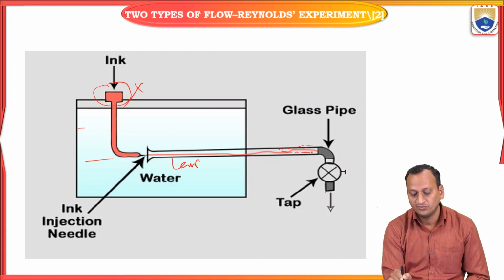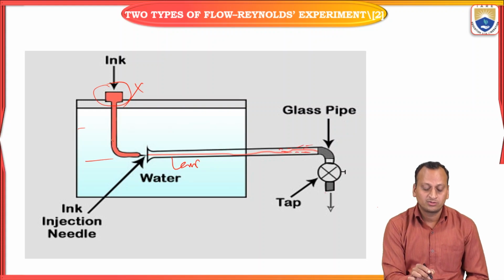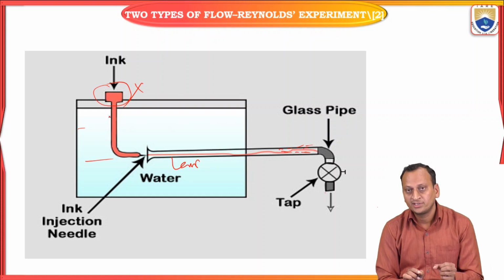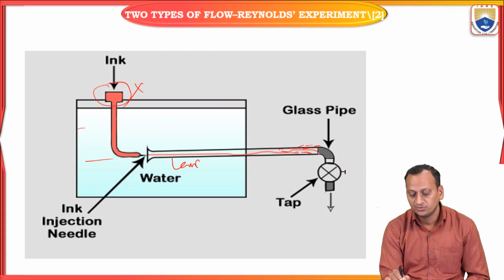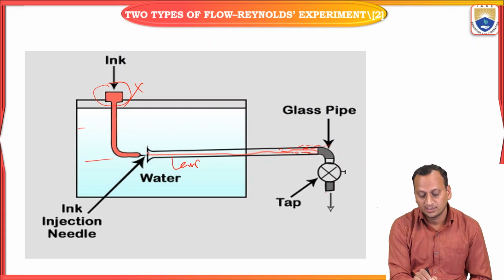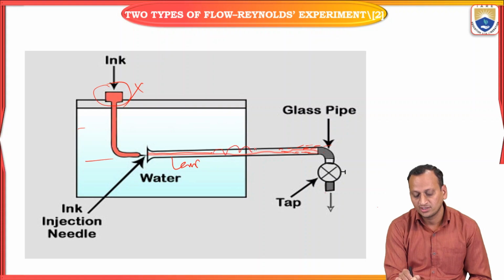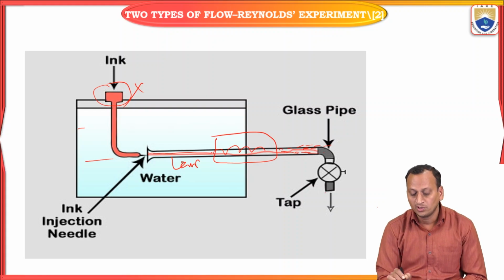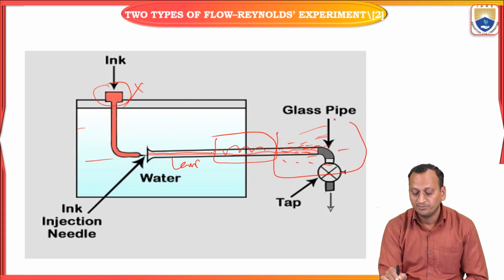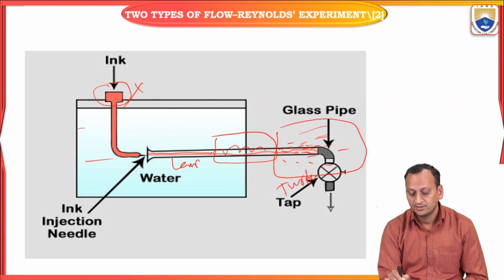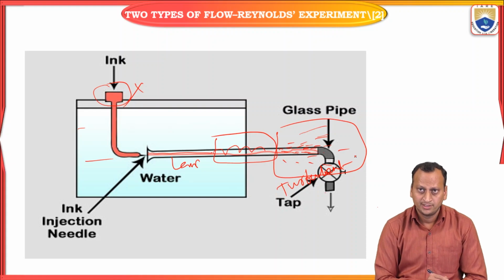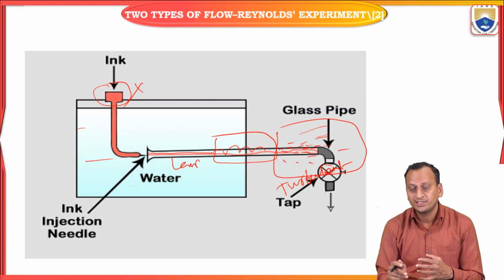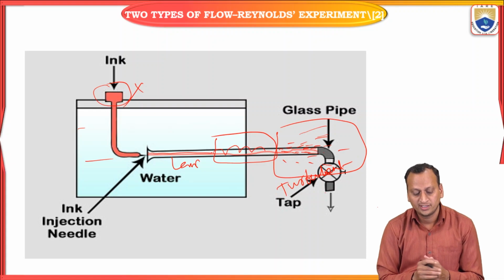The fluid which we are transmitting through a separate container with a different color, the dye, becomes diffused, whose fluid particles become diffused. So here the liquid dye is straight. Afterwards it becomes wavy, where it is a transition zone, and before that it is a laminar zone. If you open further, then the wavy one becomes diffused and scattered. Therefore you can recognize this as the beginning of the turbulent zone.